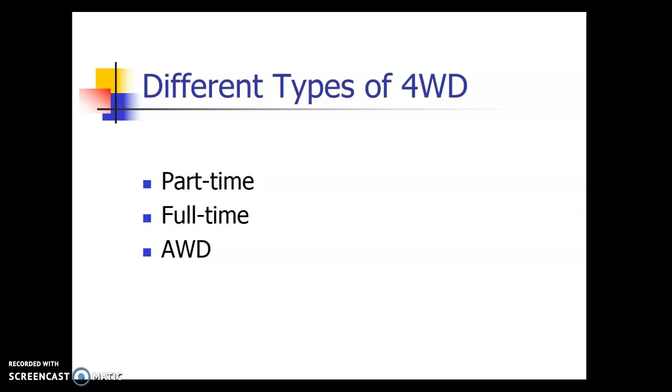Full-time four-wheel drive is kind of like part-time. You still get to go in four-wheel drive high and low, but it's full-time. It's always four-wheel drive. It has a differential setup in its transfer case that allows a difference in speed front to rear, which I'll elaborate on in a minute.